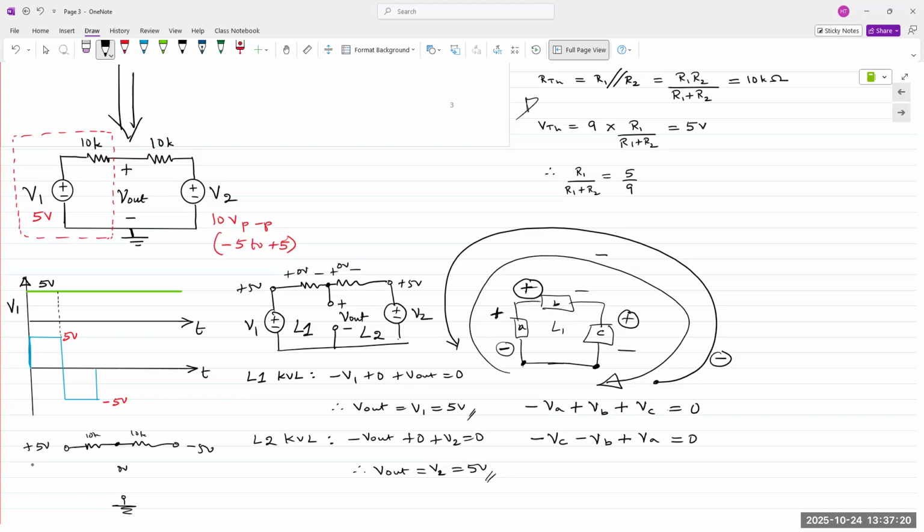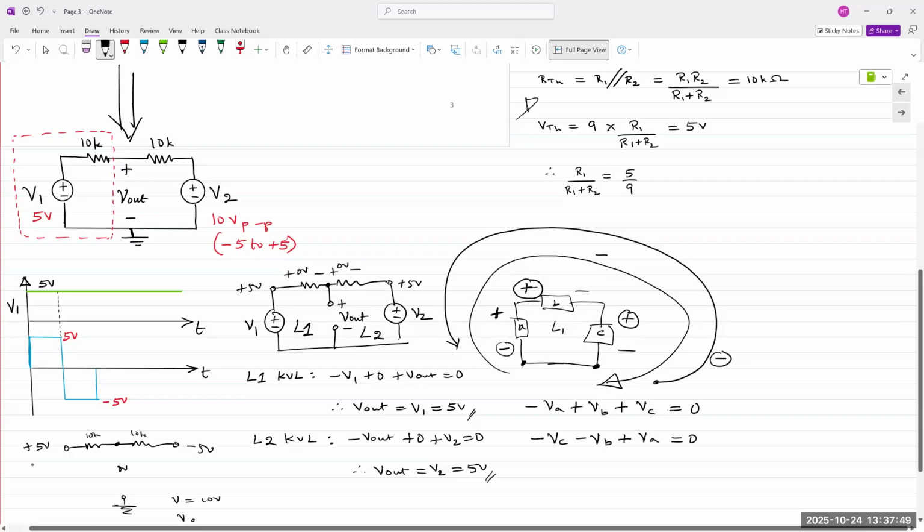So this is an interesting little problem. If you want to broaden your understanding, take a sheet of paper, simulate this in LT-SPICE, and analyze both half cycles, as I've just done. You have the analysis for the first positive half cycle, and you also have the analysis for the negative half cycle. Here the difference is 10 volts, and so V out would be equal to 0.